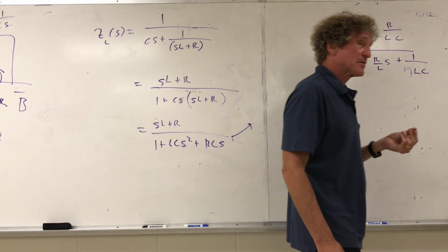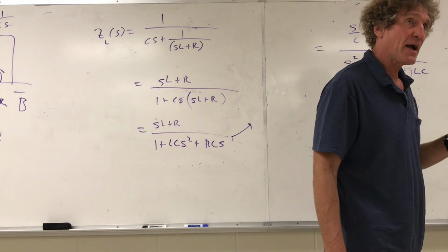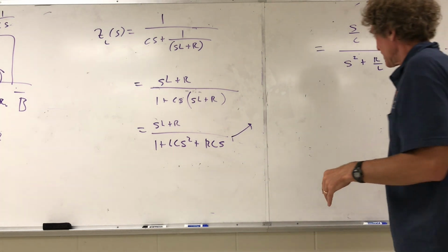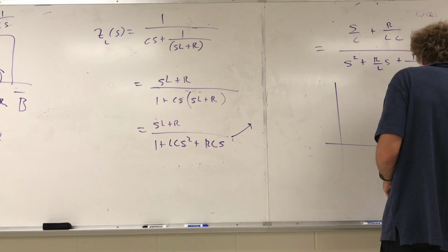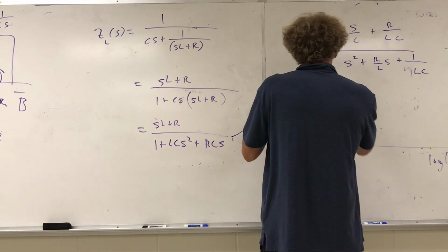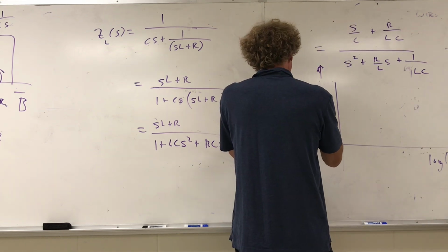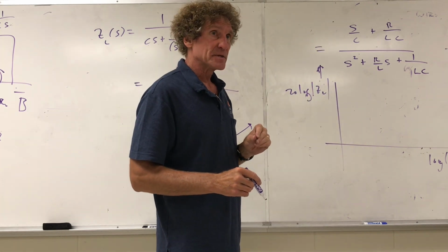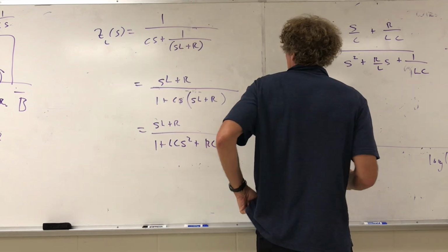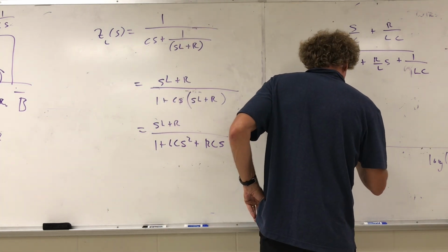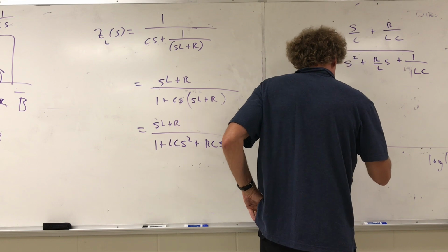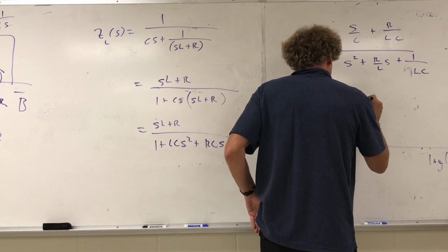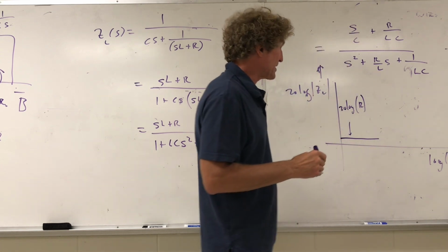So really for an inductor, which is different than the other one, you don't have a low frequency cut-in per se. This is the typical plot you associate with an inductor. If this is the log of the frequency, and this is going to be 20 times the log of the impedance of the inductor here, what actually happens at very low frequency for an inductor, you're going to have something that looks like this. It's going to be very low. This is going to be equal to 20 times the log of that resistance, and it'll be constant.